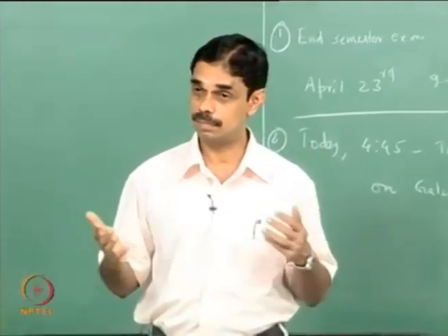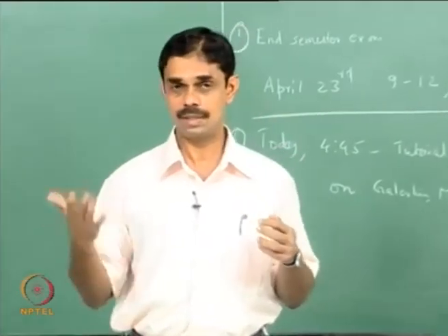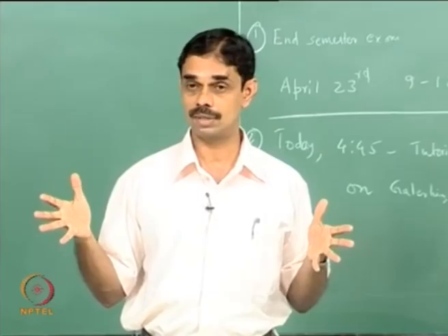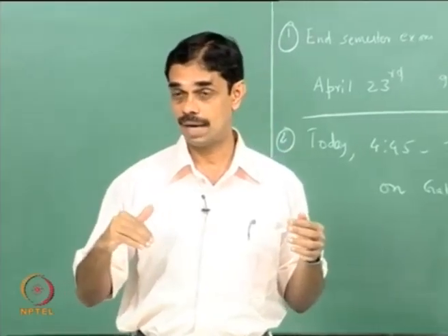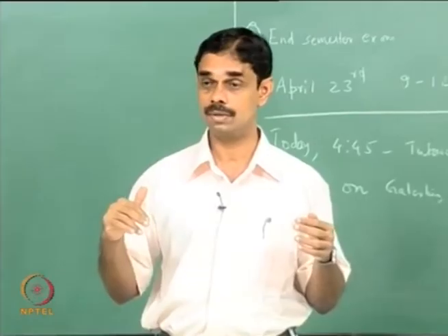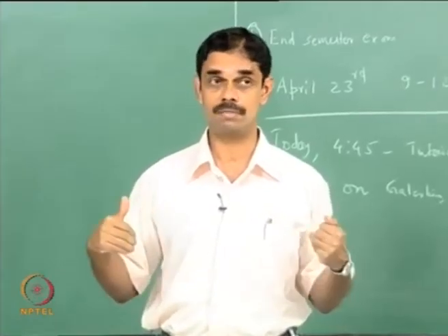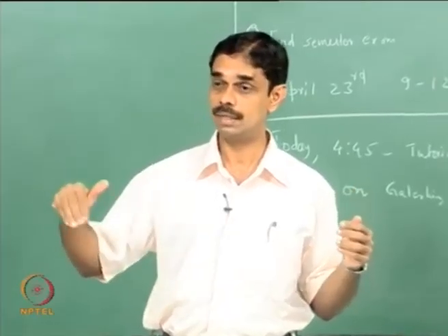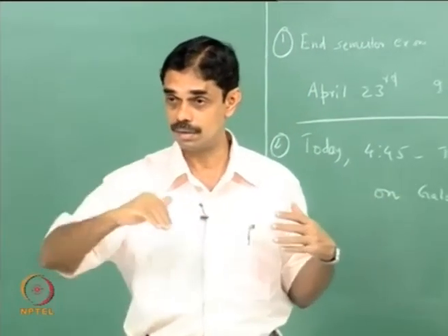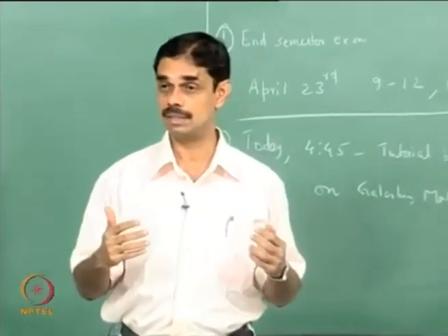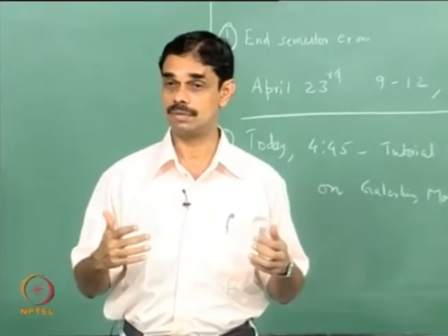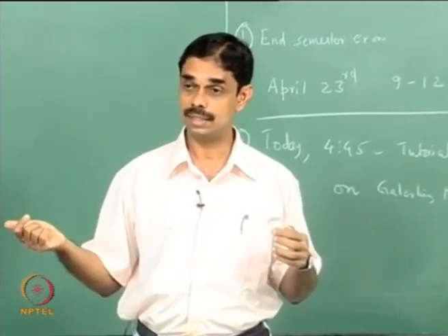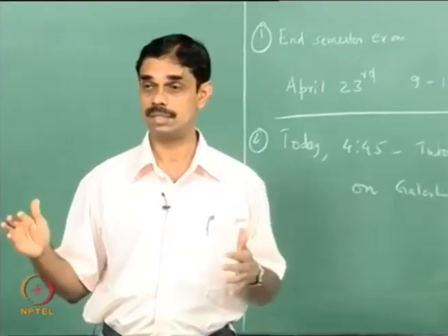Whereas we looked at premixed flame, where actually the pressure dependence is very weak, but it is mainly a velocity fluctuation dependence. Velocity fluctuation affects the flame by some kind of wrinkling, and we also constructed a model by solving a kinematic model. We solved the G equation, we solved for the wrinkles, and we saw that the wrinkles propagated up, and there was a time lag associated with it. We actually derived an expression for the wrinkle, and from there we can get the area fluctuations, and then we said that the area fluctuations translate to heat release rate.